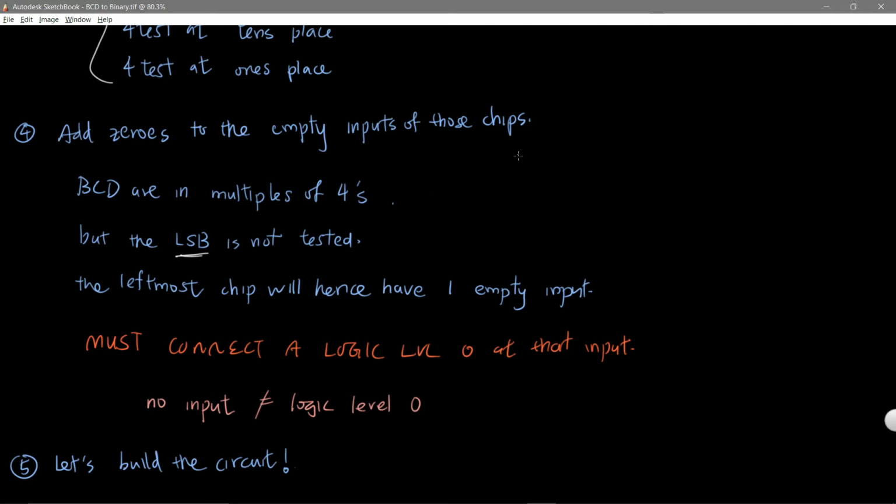To go through in detail, some of the logic gates are implemented with transistors, right? So if you have a NOT gate here, this is the power input, this is the ground, this is your signal input, and this is your signal output. And the NOT gate in real life actually has 4 pins instead of just what we learned for 1 input and 1 output, and those 4 pins include power and ground.